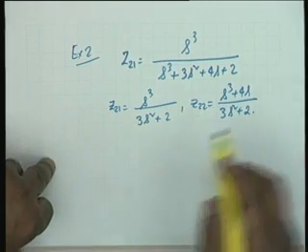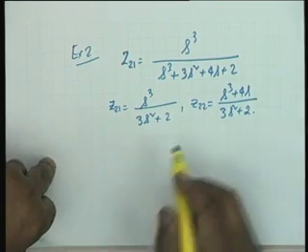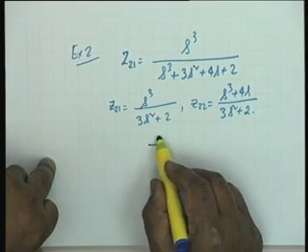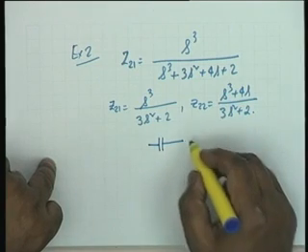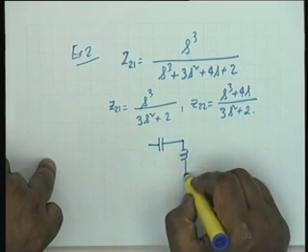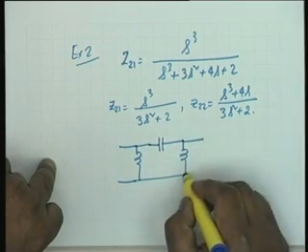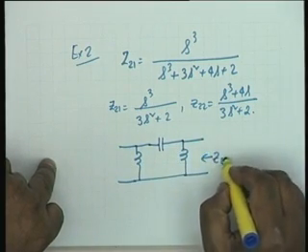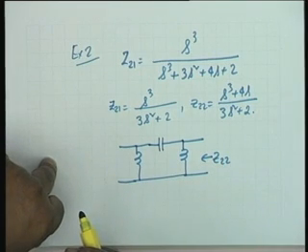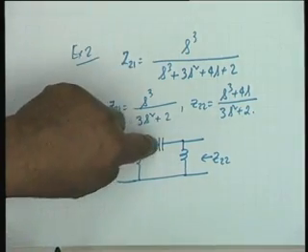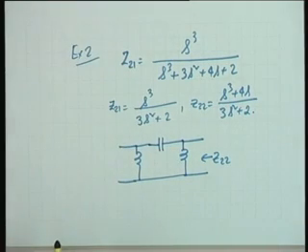Now the structure that I want, with transmission zeros at the origin, is a series capacitor and 2 shunt inductors, 1 and 2. This is what I want Z22 to be. Agreed? You have to guess this structure. 3 transmission zeros all at the origin. So series impedance pole, 1 capacitor and 2 inductors. It could not be 2 capacitors and 1 inductor.